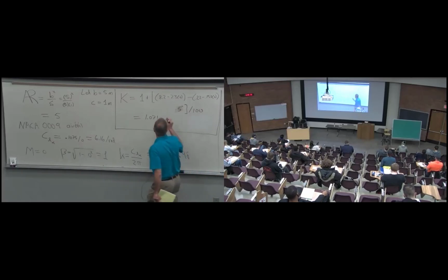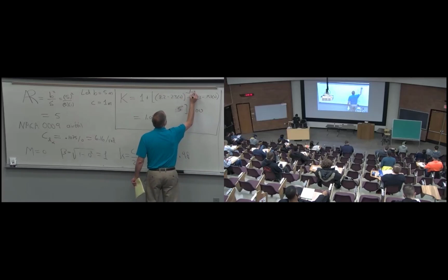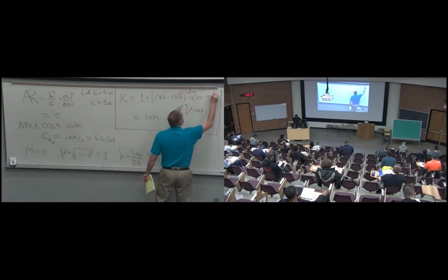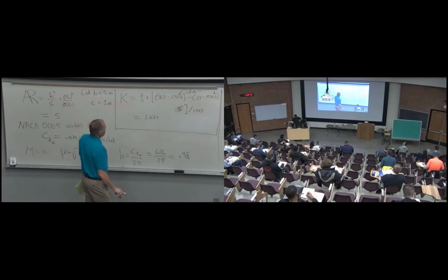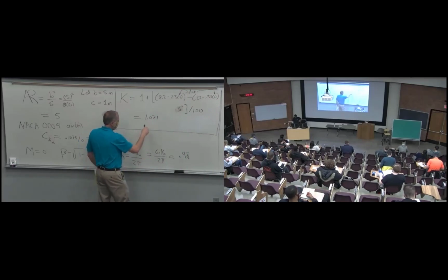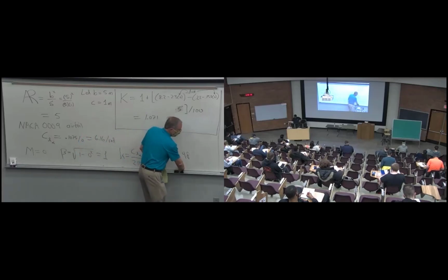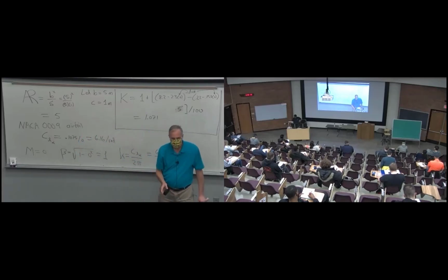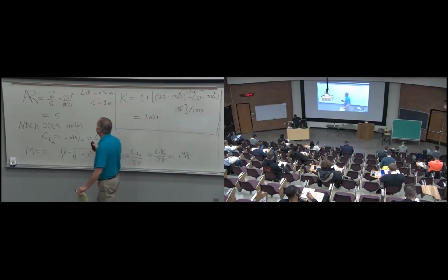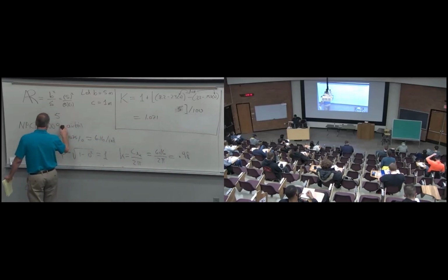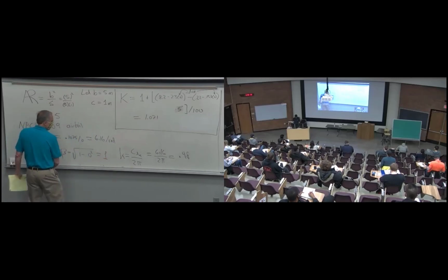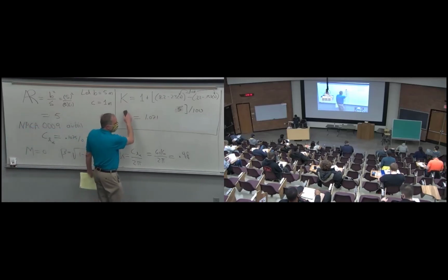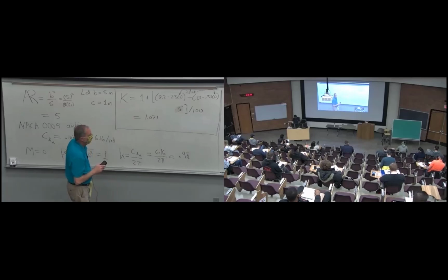And this thing here where I put in the zeros, this is the leading edge sweep angle here and here. You can see that from the formula. So I'm just plugging in numbers and I get this value, and now I need to go to the big formula. So I've got everything I need. I got the aspect ratio, did the airfoil, got CL alpha, got little k, got beta, got the Mach number, got the big K. I think that's everything I need for the formula.